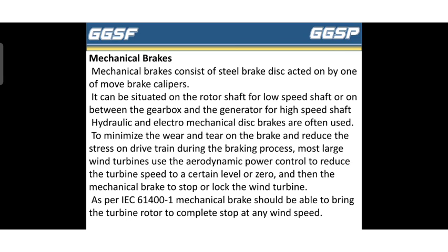Most large wind turbines use aerodynamic power control to reduce speed to a certain level or zero, and then the mechanical brake to stop or lock the wind turbine. As per IEC 61400-1, the mechanical brake should be able to bring the turbine rotor to a complete stop at any wind speed.